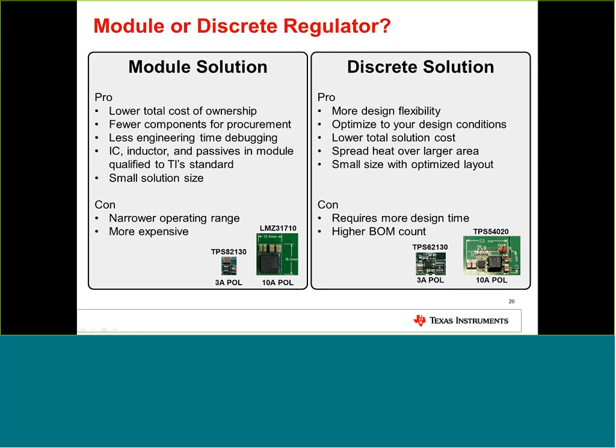And yeah, depending on the experience of the engineer, it takes you less time to provide this complete power solution for your FPGA supply for the FPGA rails. And of course, with the module approach, you can really achieve the smallest total solution size. But again here, the negative aspects: it's more expensive and maybe it narrows down the operating range.